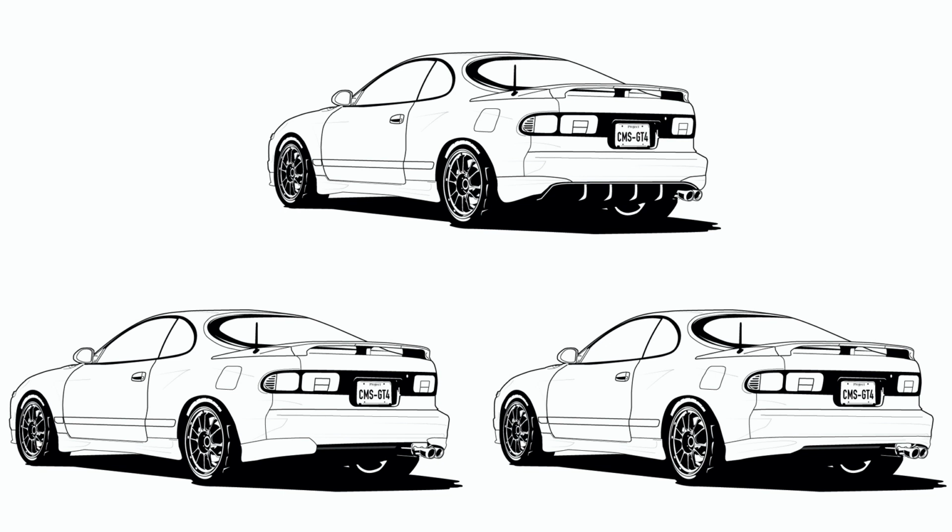And then on the bottom left is the same concept with the SS3 spats. So this is more along the lines of how they would fit. I had a set at one point that I experimented with. They do bolt up. Now, at the fender area, they don't fit quite right because the fenders on the 6th Gen are flat where the fenders on the 5th Gen are rounded. But it also sits a little too low on the bumper. So there is a company that makes fiberglass ones, and I think those would be a good candidate for changing the mounting position on and doing a little bit of shaving and blending to make it work better with our bumper. And that's what this actually is on the right.